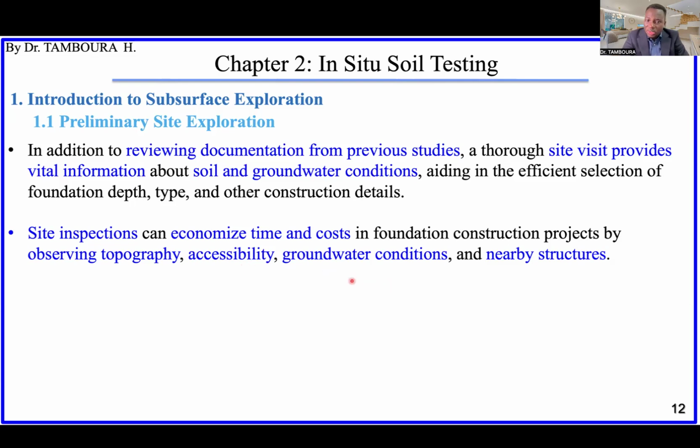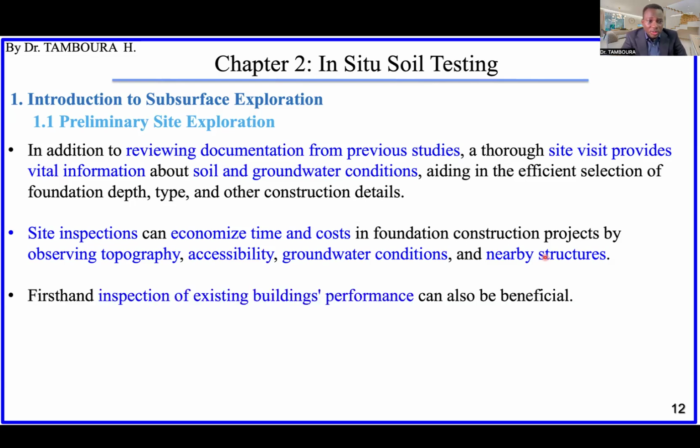Groundwater condition, and as I said, neighboring structures. Maybe the maps you have are a little bit old, or the documentation you have is old. Maybe there is a new structure being built just near the place you want to build. There are some details only the site inspection can give.